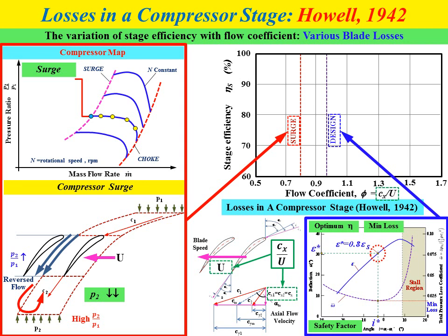Because we already set the compressor parameters to obtain a certain value of pressure ratio, the compressor will make a compensation process where it tries to re-increase the pressure so that the pressure difference will be increased and achieve the value that we set for the compressor operation.